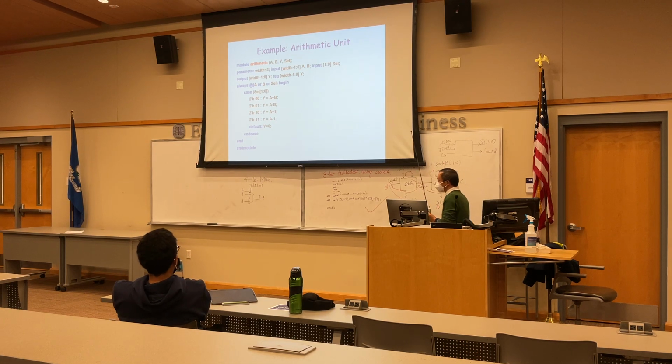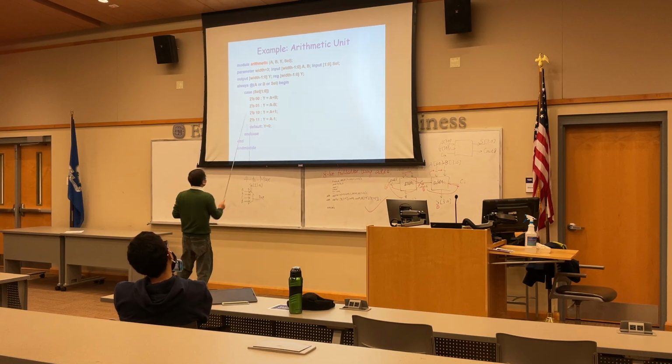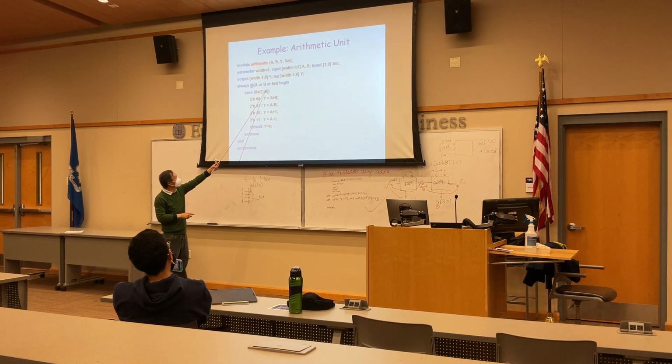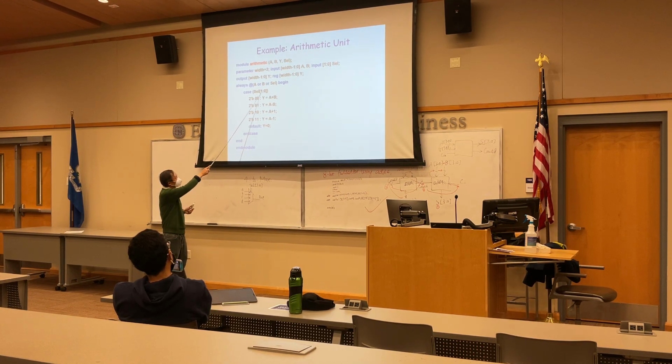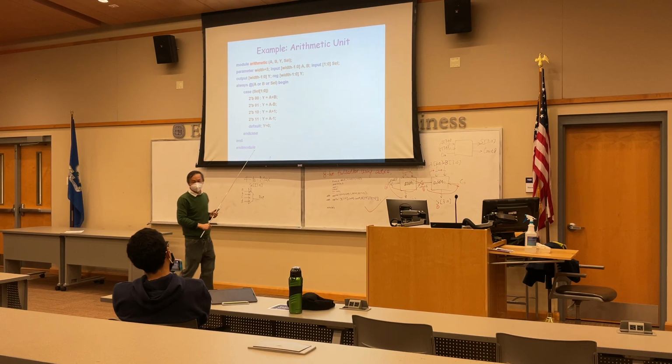ALU, using the case statement. Sensitivity list. So the selection bits, select mode: 00, perform addition, go to Y. 01, perform subtraction, go to Y. 10, increment by 1, go to Y. 11, decrement by 1, go to Y. That's the ALU.